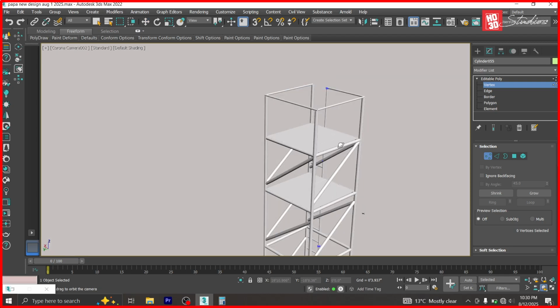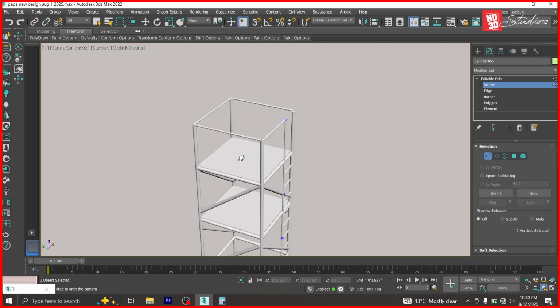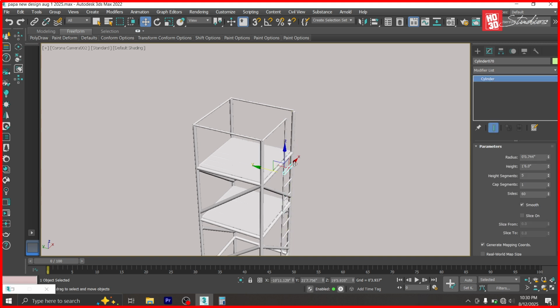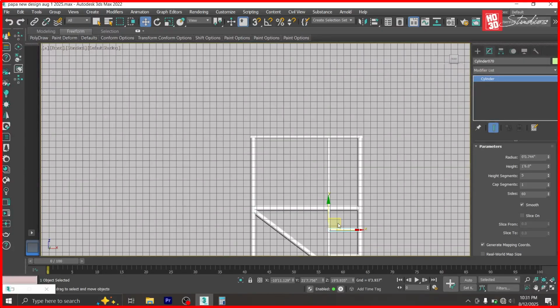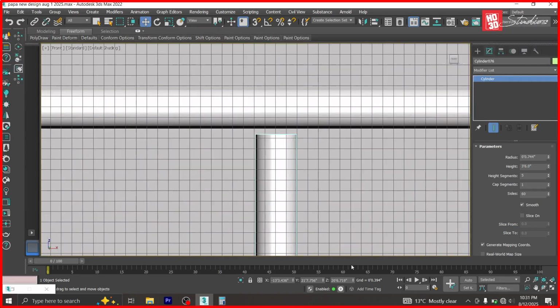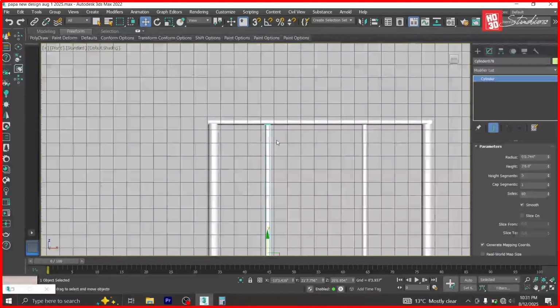You can see. So now we're going to use 1.5 foot pipes to create braces. So let's take one of the rungs, hold shift down, it clones it. Let's right click it and put 0 here. Yes, good. And let's call it height. We're changing this height. The height originally was 1.5. So let's change it to 3.5. Good. And let's bring it here.